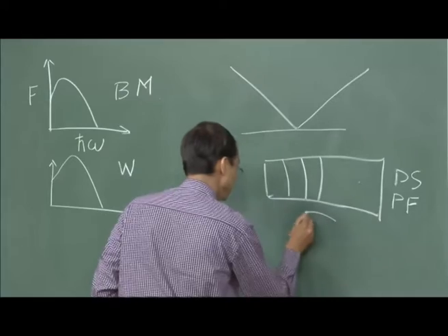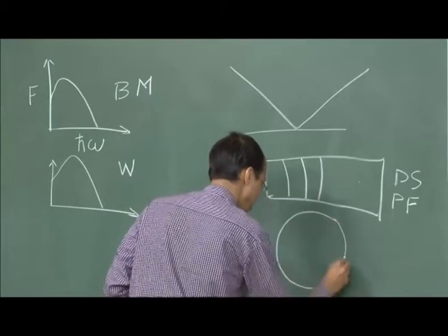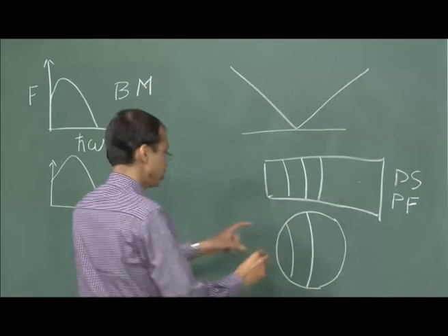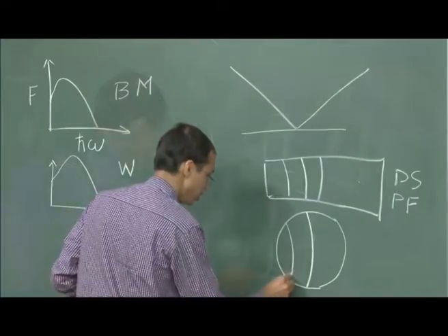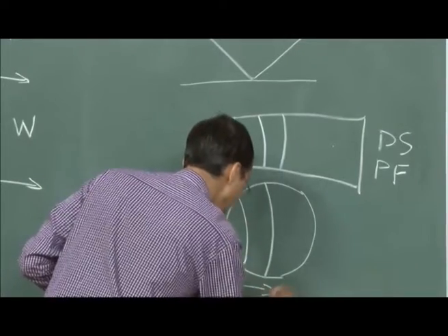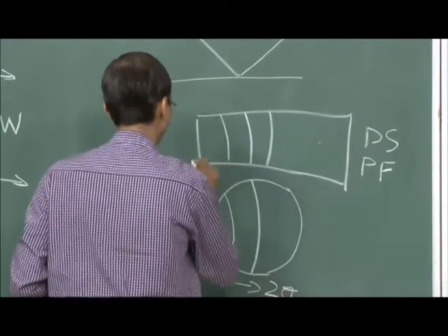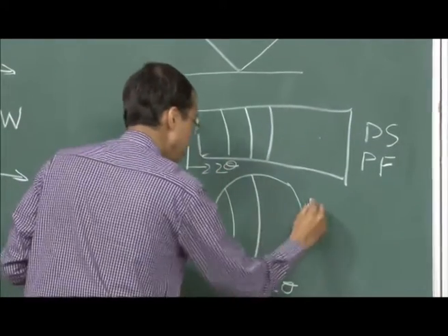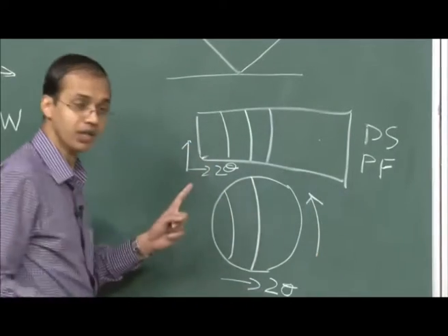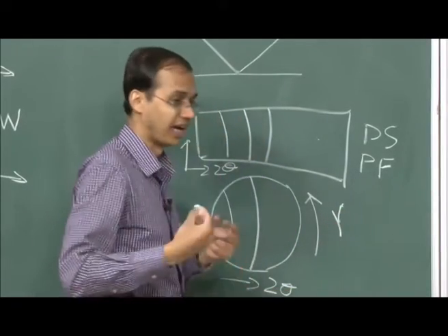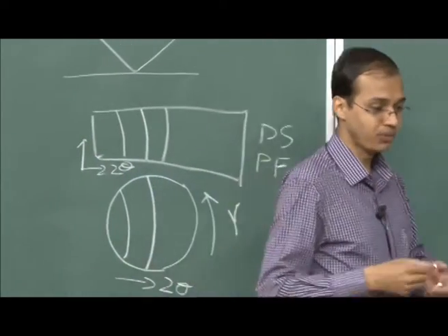Instead, what we have is a nice area detector which covers a large area and shows me patterns like this, which are nothing but the intersection of my diffraction cones. So, these peaks give us information not only in 2 theta, which is shown over here, but also you see there is another angle over here from which you are getting information. This information corresponds to what is known as the gamma or chi angle, which we had talked about, and corresponds to the orientation of the sample.